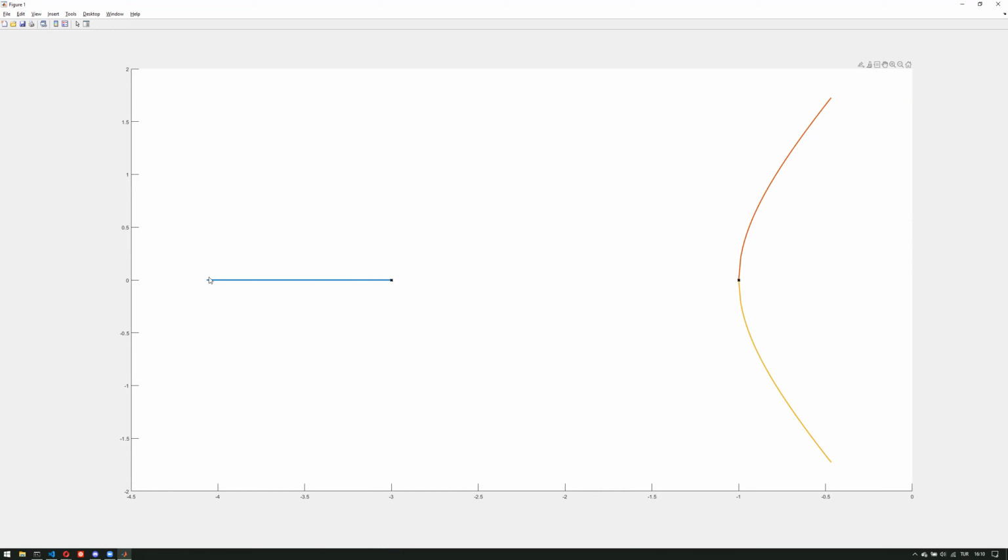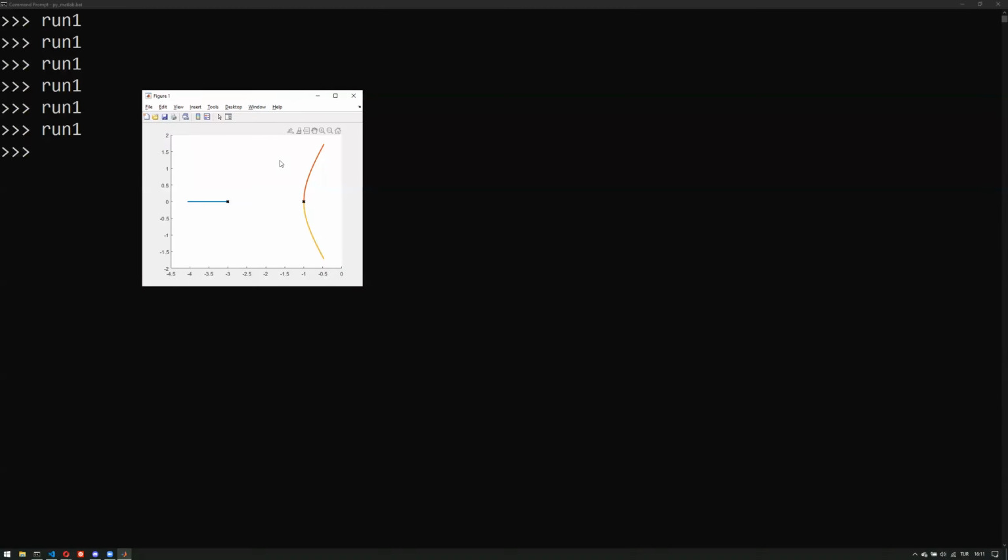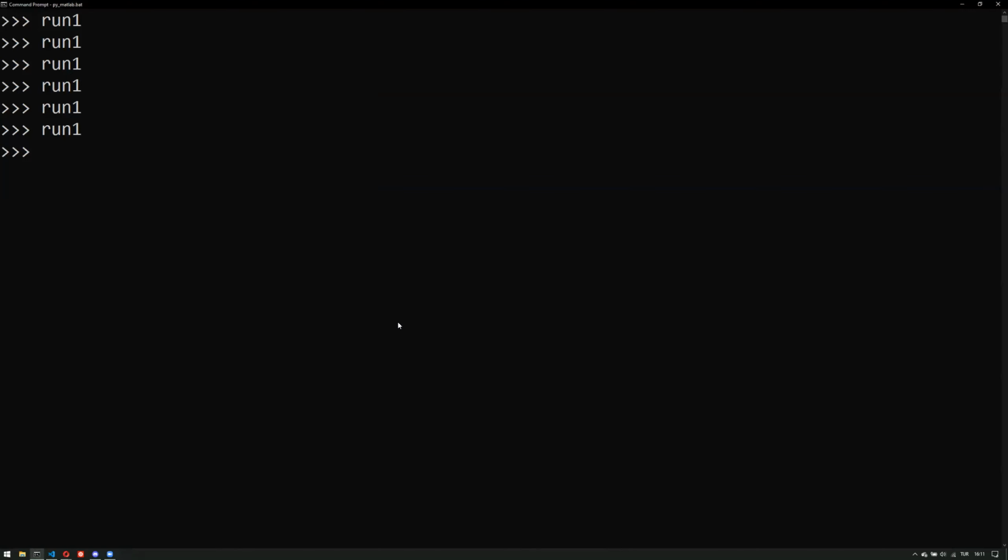So if we increase k, we see that the system has a certain behavior. Now, looking at this, we can go ahead and plot step responses, choose a certain one of them, and then use that k value. But it seems like it's not really wise to increase the k value here, because it will become more oscillatory, because the zeta value, we will talk about this all the time, is decreasing, so overshoot will become larger and larger. Now, the root locus plot is basically done.